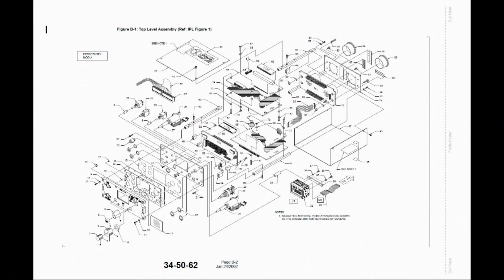And aircraft are now decked, meaning the distance height-wise between the 2 aircraft is 1,000 feet. That's, you know, onion skin distance when you're traveling at 350 knots, approaching each other. But the systems are so accurate that if for whatever reason you're close, it'll tell one pilot descend, the other one ascend, in order to avoid collisions. You don't hear of aircraft flying into each other, rarely, and it's partially due to this.